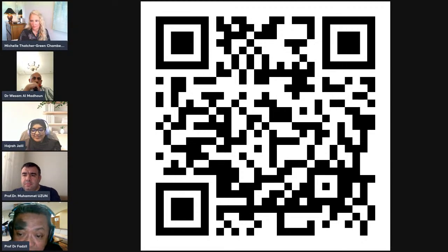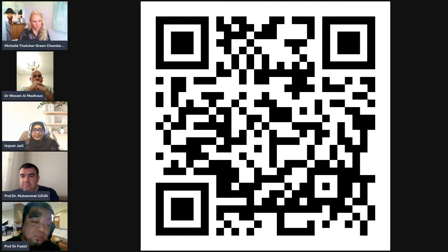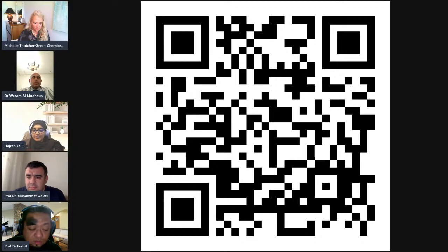Okay, we're talking about the utilization of recyclable concrete with aggregate recovery and rehydration integrated with CO2 utilization. There is some research that has been carried out. Even I myself and my team are also doing research on recycled concrete aggregate. The main problem with recycled concrete aggregate is that most of the recycled concrete has been dumped in the same area without caring about the quality of the concrete. Normally concrete has different grades. In the first place, if we can separate the concrete grades, from that we can categorize the quality of recycled concrete aggregate. Maybe we can state it as grade 1, grade 2, or grade 3 recycled concrete aggregate.